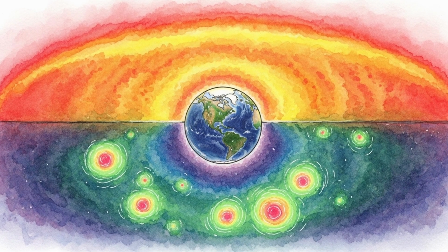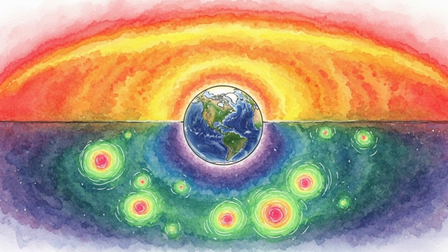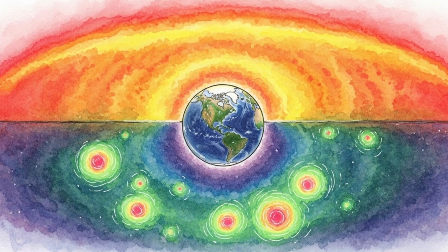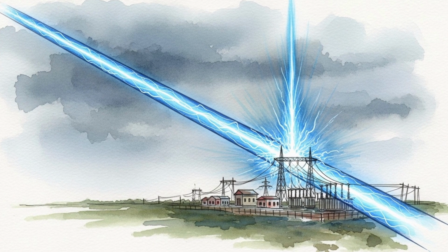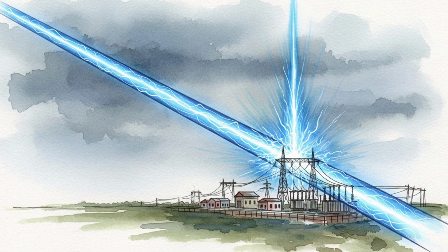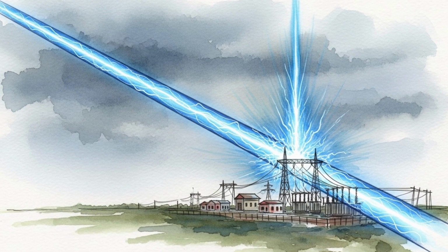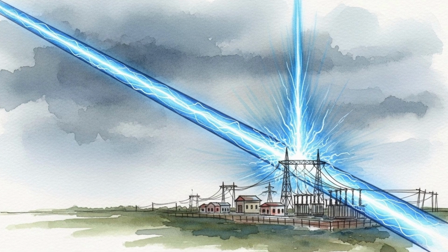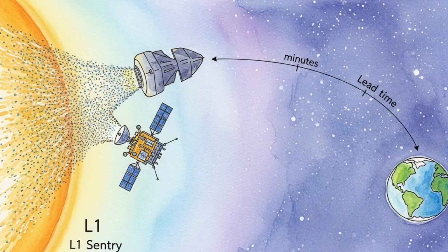During extreme storms, auroras expand to much lower latitudes than usual. Historical notes, ship logs, and newspaper reports describe displays far from polar regions. This geographic spread is a practical proxy for the strength and reach of the ionospheric current systems. When auroras are seen at low latitudes, long conductors far from the poles may also be exposed to significant induced currents, even if the absolute magnetic perturbation is moderate.